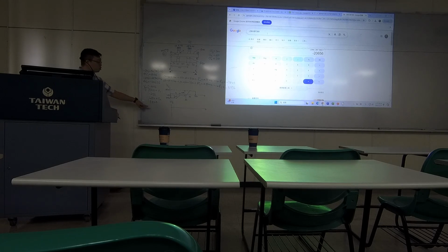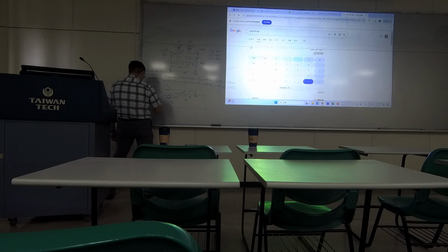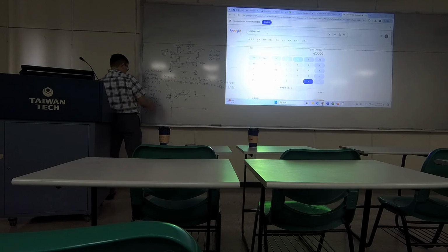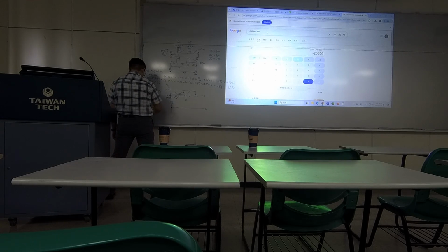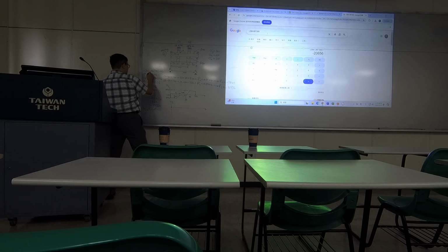So if you do the integral, you will get all the equations you need for the moment. So the moment part will be negative 3376x. You don't need a plus constant anymore because based on the boundary condition, here it is 0. Okay, so that's it. The next part would be 26x squared plus C1, so minus, I forgot the negative sign here.